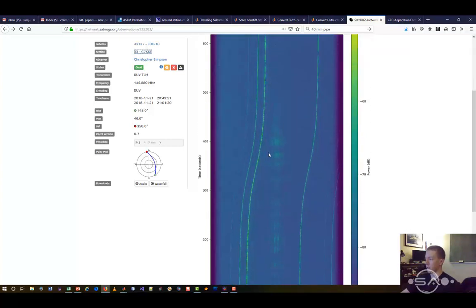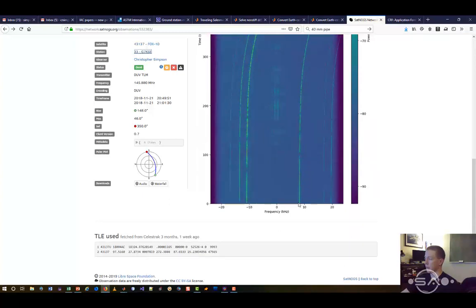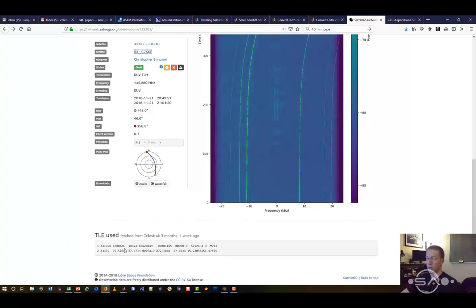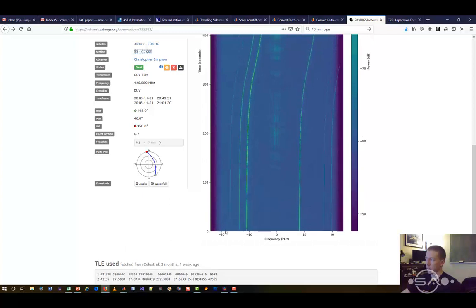And it's not down the center. So if you look, it ends up at -10 and shifted inside of 10. So if it's not directly on 0, because this is a centered frequency, then the TLE used, the two-line element, which provides us with all of our orbital elements, drag terms, everything we need to propagate forward in time, might have some error that we have to account for. In other words, our observed won't match our computed from our TLE. And so this is an example of it in real life here.